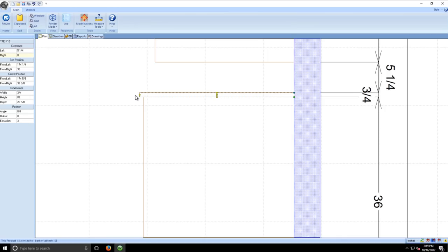If you try to make it too flush, if you try to put the face of that door and the face of that in panel flush together, it works sometimes. But if you have to adjust your hinges on tall doors, it can be a problem, and it draws the eye to the imperfection. So we always do 5/8 proud. That leaves an 1/8 of an inch back from the face of the cabinet, but it also covers the side, so it's kind of the best of both worlds.